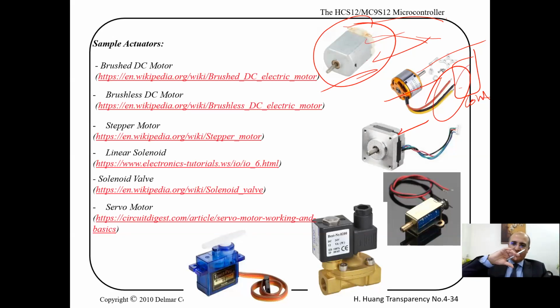But if I want a motor to turn to a certain angle and stay there, or while it's running or turning, be able to know how far it turned, the omega, the angle it turned. You can know that because this is controlled in a different way. It has multiple wires. If these are 4 wires, for example, to start you need to write a for loop, for example, and write a 1 0 0 0. This will make the motor turn a step.